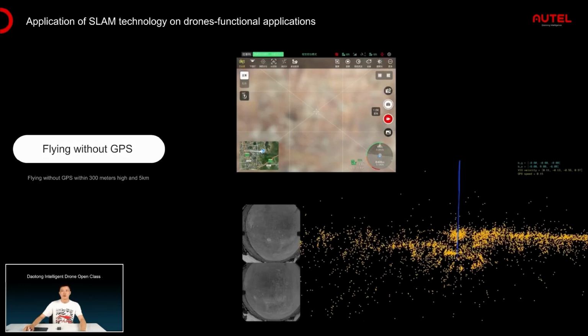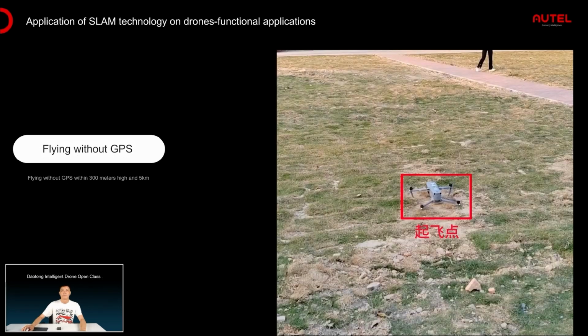In our experiments, we employed anti-drone technology to disrupt the image transmission signal, illustrating how it gets disconnected due to such interference. Despite the lack of GPS signal, our aircraft is unaffected because the jamming device cannot disrupt the SLAM system. SLAM operates based on internal sensors, offering a significant advantage over GPS reliance.